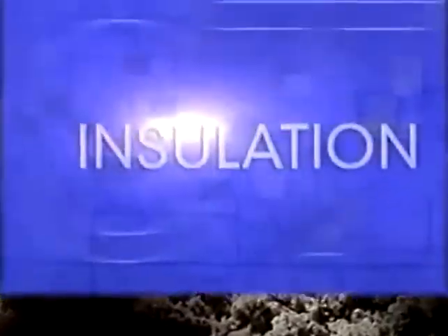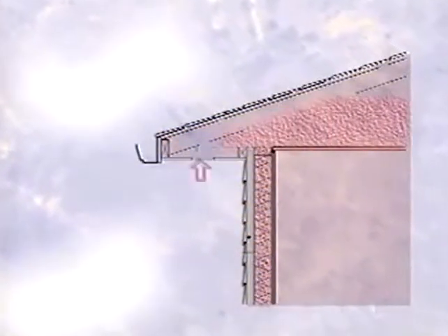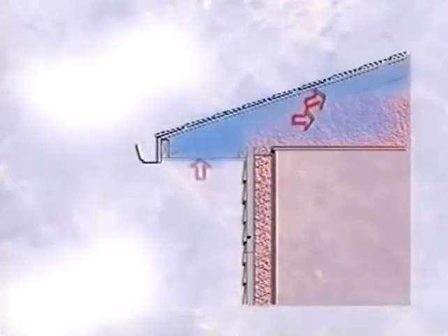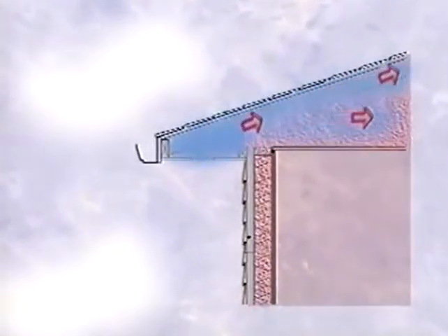The insulation of attics is extremely important. Here we must balance proper ventilation with proper insulation. In a typical attic, you will find insulation pushed to the outer edge, exposed to the outdoor air which comes in through the soffit vent. Because insulation is not an air barrier, the wind can enter the insulation and leak into the conditioned space. This problem is known as wind intrusion.